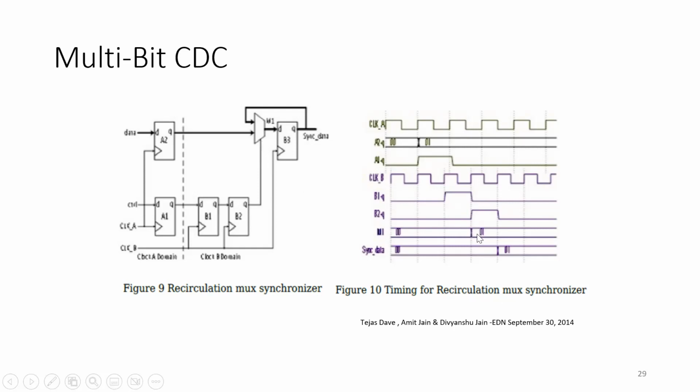I am selecting to go to the new data that is available in here. After I get this, it will go low. Low means remain as is, no change. When this input is low, I keep the same data until I reach another control signal to get new data.